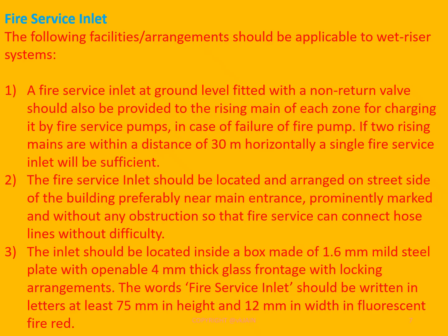2. The fire service inlet should be located and arranged on the street side of the building, preferably near the main entrance, prominently marked and without any obstructions so that fire service can connect hose lines without difficulty. Fire service means fire brigade or the local fire service.